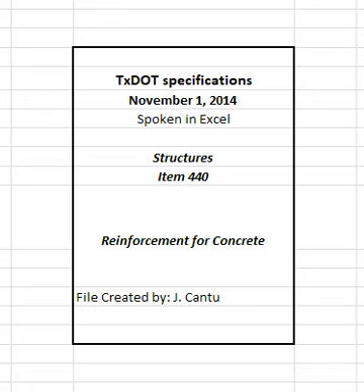2.12 Dual coated reinforcing steel. Provide deformed bars conforming to ASTM A1055, grade 60 or higher when dual-coated reinforcing steel is required on the plans. 2.13 Glass fiber reinforced polymer bars, GFRP. Provide bars conforming to the AASHTO LRFD Bridge Design Guide specifications for GFRP reinforced concrete bridge decks and traffic railings, Section 4. Material specifications when GFRP bars are required on the plans.